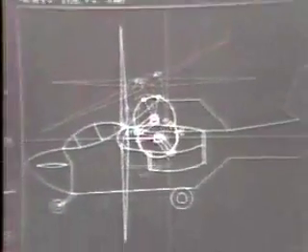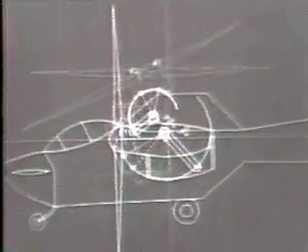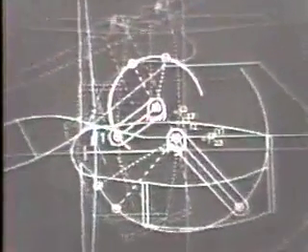Now the designer has 3 design positions and is positioning a moving pivot for a 3-position synthesis. As the designer moves the moving pivot out onto the display area, the 2nd and 3rd positions of the moving pivot are also shown, and the computer displays the link which it is instantaneously synthesizing, capable of guiding the moving pivot from its selected number 1 design position through the other 2 required positions.